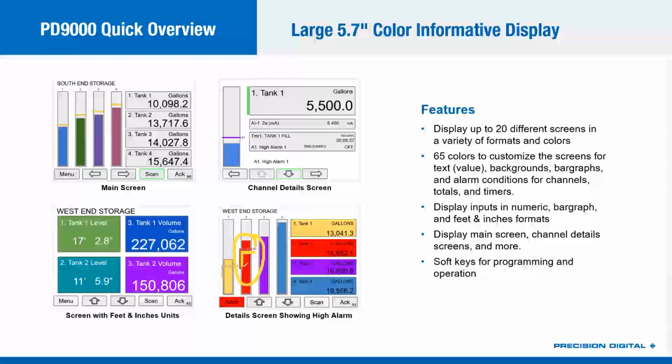But now that my alarm is active, I have a vertical bar there that shows me the deadband and when it's going to reset. And when you enter that alarm state, I can have the bar graph, the text, the background for that text, change color, flash, do all sorts of things to draw your attention to it. And we automatically give you an alert button on the lower left. You can push that alert button and it'll tell you what alarms are active.